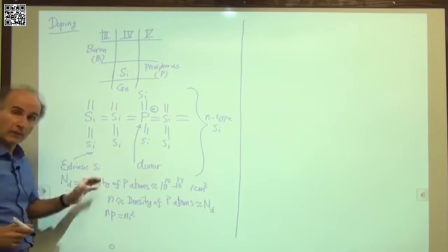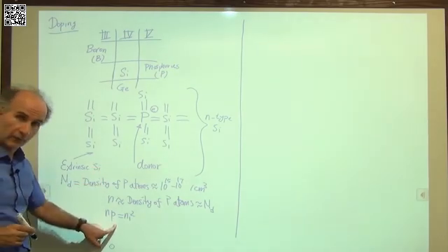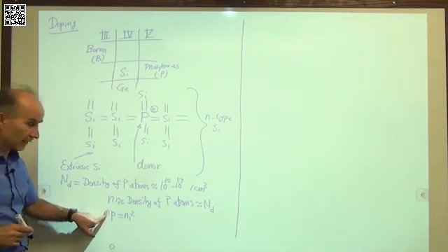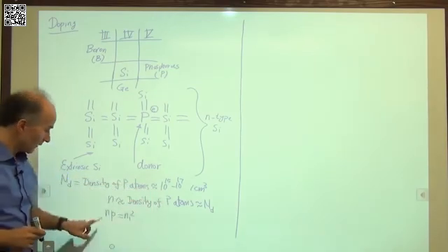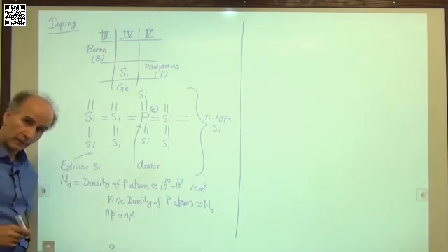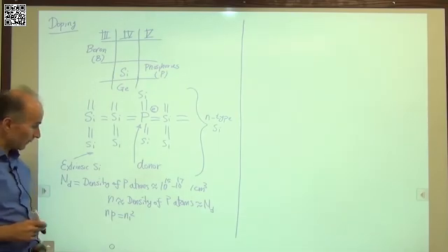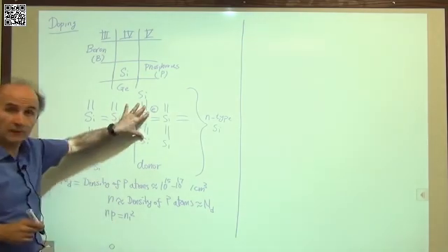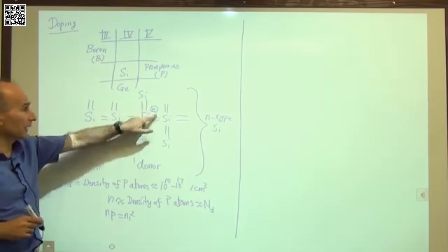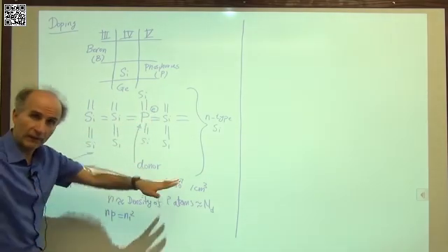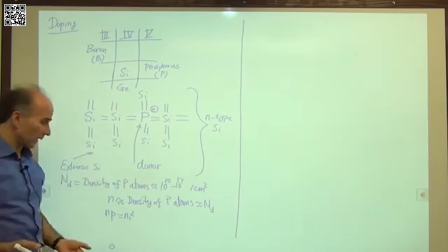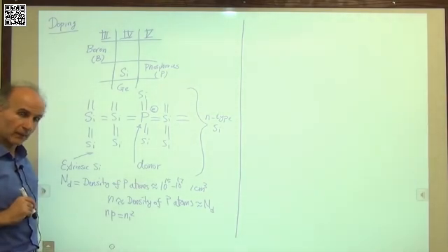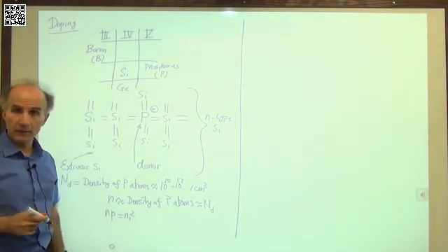Even this is no longer pure silicon. Of course, we saw that for pure silicon before. But even though N has gone up so much, N used to be 10 to the 10, now it's, for example, 10 to the 15, this product is still equal to Ni squared, the Ni that we had before. Why is that? Well, because P goes down so much, the number of holes available in this piece of silicon has gone down. Why? Because these free electrons that came out of the phosphorus atoms very easily went and filled those holes. So the number of holes is much smaller, and that's why N times P is still equal to Ni squared. All right, so this is what we call an N-type piece of silicon, which is doped to give us more electrons.